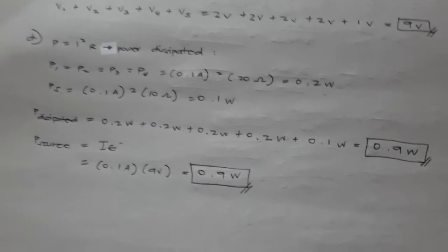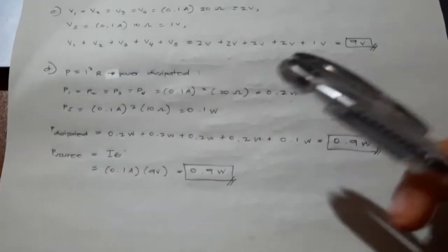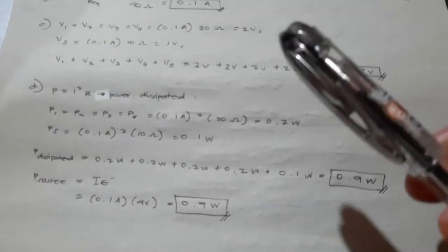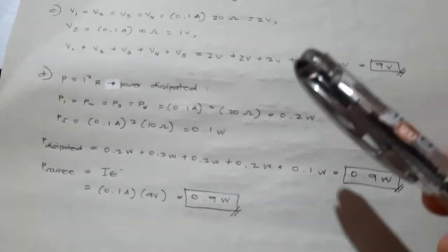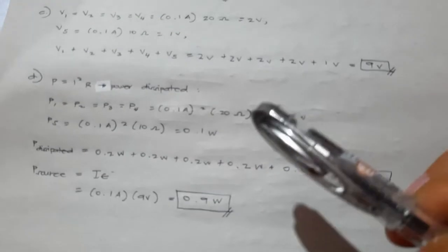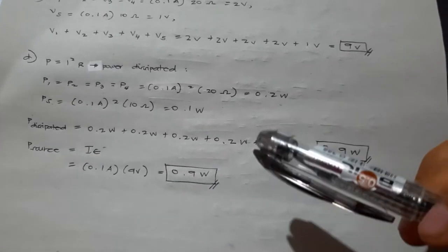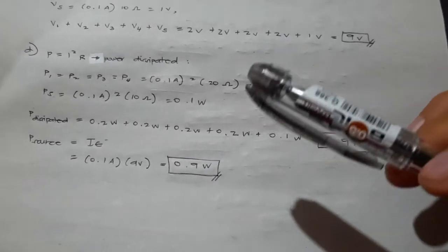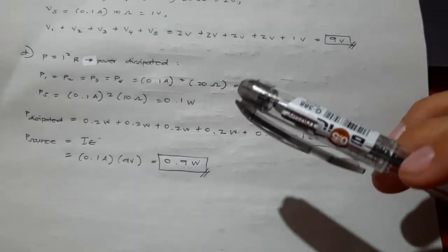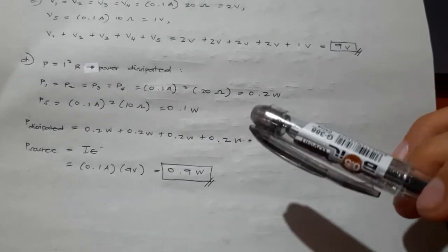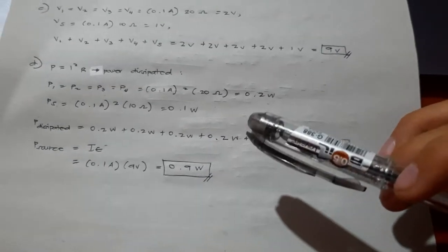So these are the several reasons why we would use multiple resistors instead of just one resistor with a resistance equal to the equivalent resistance of the circuit. Perhaps a resistor of the required size is not available, or we need to dissipate the heat energy, or we want to minimize the cost of resistors.